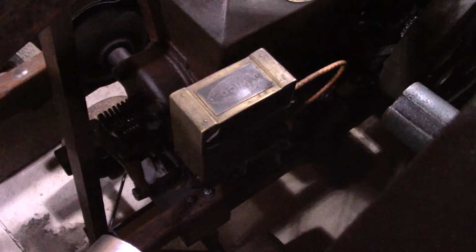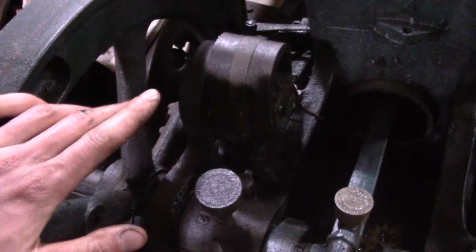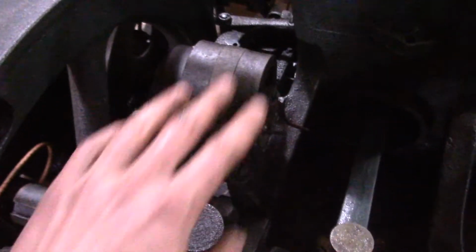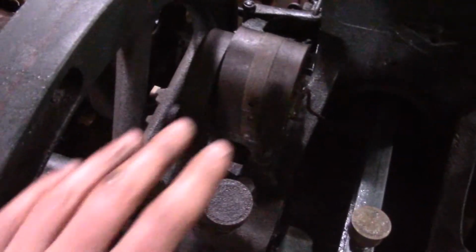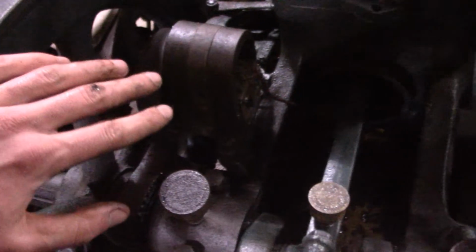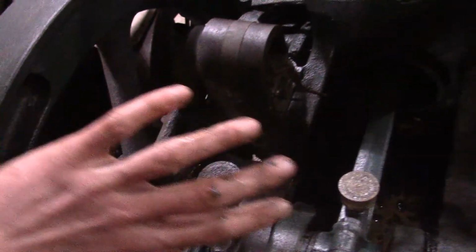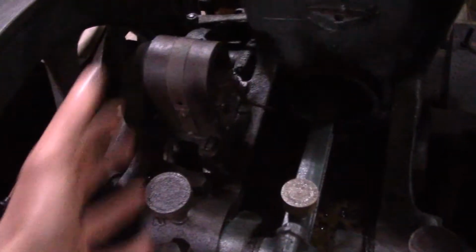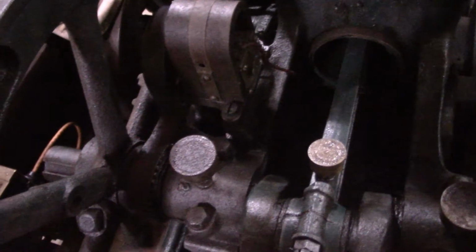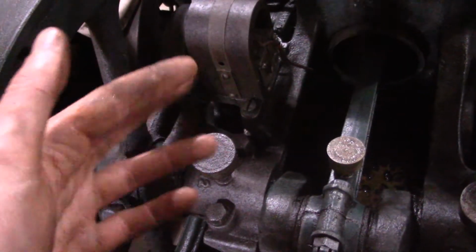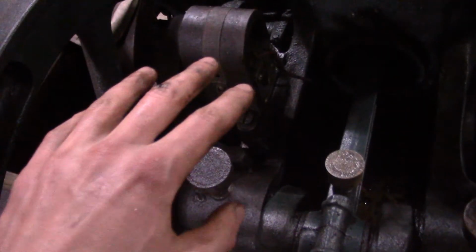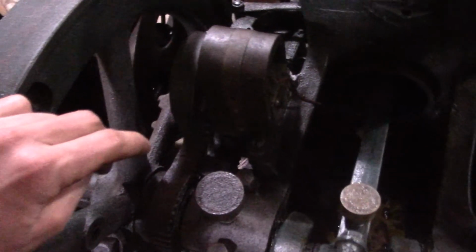Now here's an example of a magneto ignition. This is a Wico EK mag on my Stover Model KA, and this, I think, is a Model R magneto. But anyway, this is on a 3 horse Fairbanks Model Z. They all work slightly differently, but the concept is roughly the same, where there's a magnet and, of course, a magnetic field that passes through a coil of some sort, and that induces a current in that coil, and then due to a primary and secondary coil being in the mag, it creates a high voltage spark.